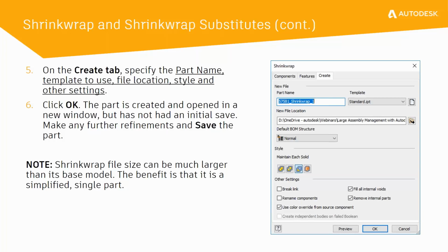Once we hit OK, it generates the Shrinkwrap component and saves the component for us. One thing to note is that the Shrinkwrap file can be much larger than its base model, but the benefit here is that it's a simplified single part.